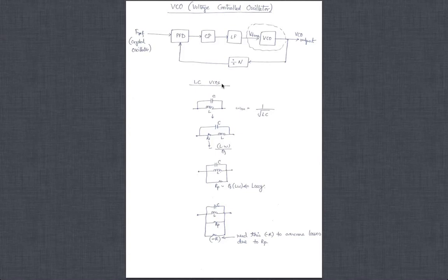If the phase noise requirement is relaxed, you can use ring oscillators in those applications. But in most cellular, Wi-Fi and various other applications, you have stringent phase noise requirements. You want a very clean oscillator. If the noise in the oscillator is less, it means it's very clean, and you tend to go with LC oscillators. So here we'll cover the LC VCOs.